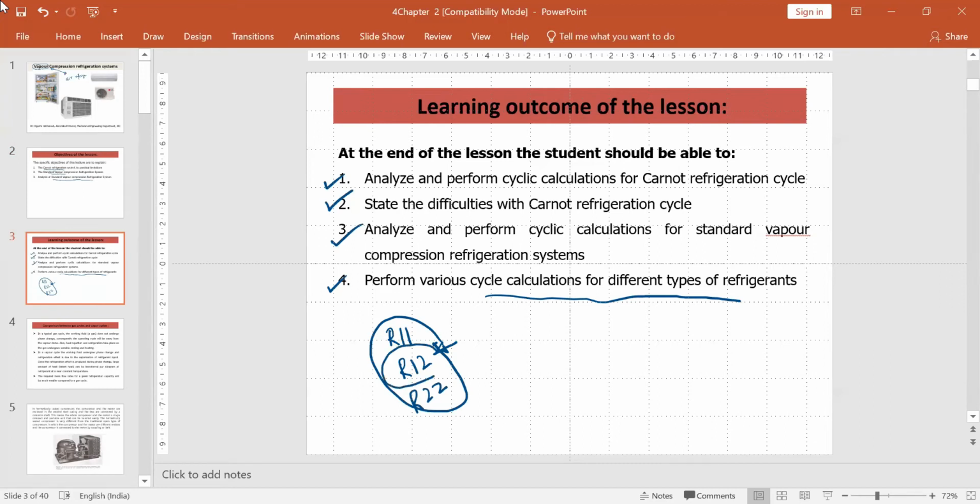But due to ODP, ozone depletion potential, the stabilized CFC creates the ozone hole. Due to this, there is the Montreal Protocol. It was decided to remove all these refrigerants which have high ODP value, and they are replaced by others with low ODP value, although they are very good refrigerants in terms of thermodynamic property.